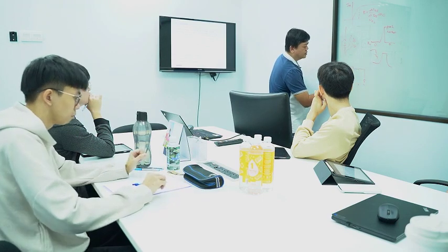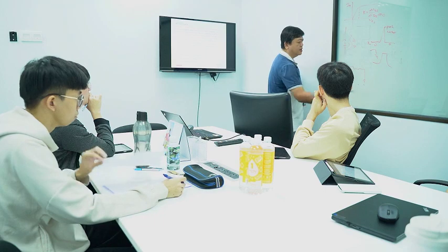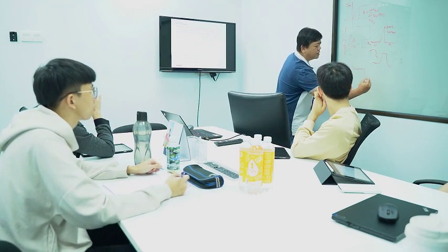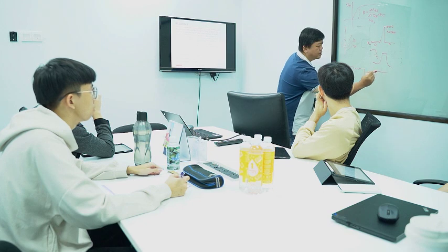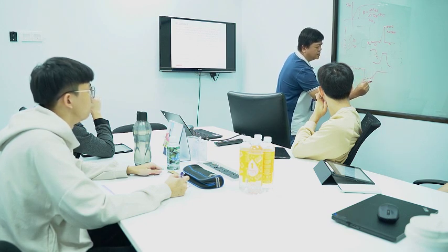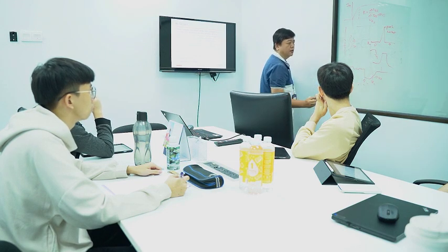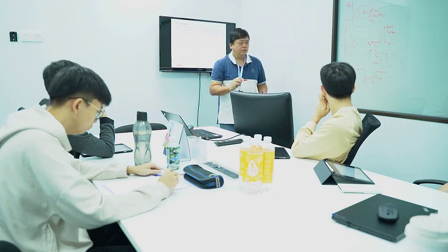You put a pulse here, 1 step pulse, right? Your output will rise up. Let's say this is 1 volt. Your output will rise up and reach 1 volt here. But at 1 RC, your output will be about 0.63 volt, right? At 1 RC, about 0.63 volt.